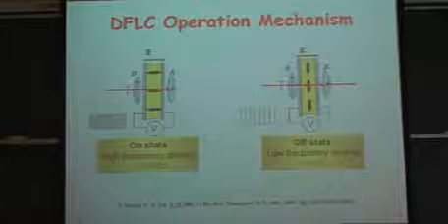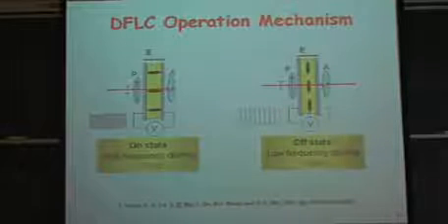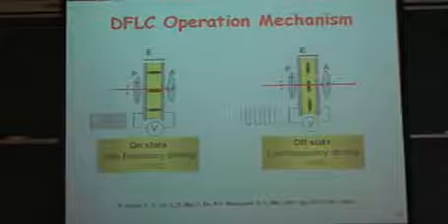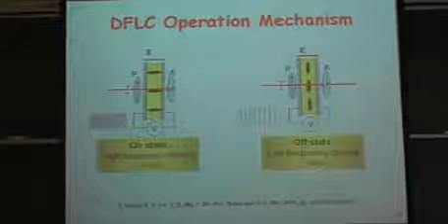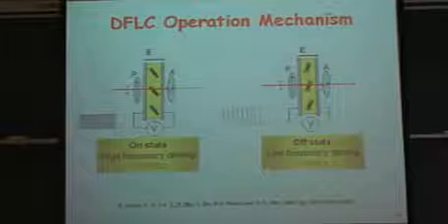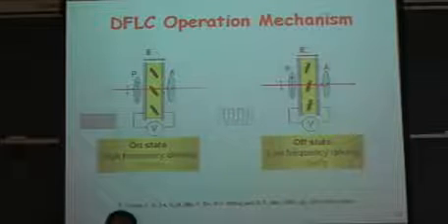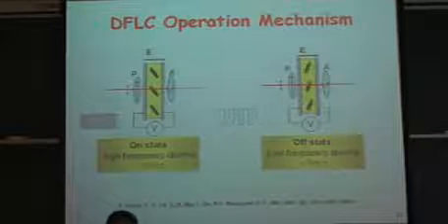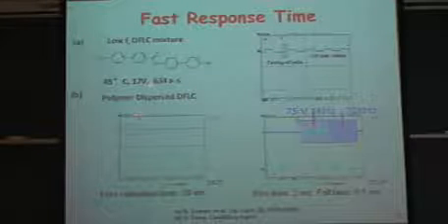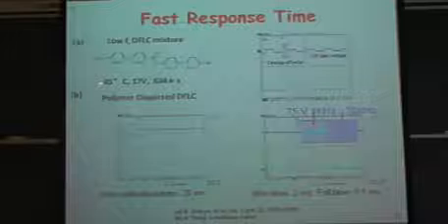Okay. Now this slide shows the dual-frequency operation mechanism. As we said before, both rise time and decay time can be assisted by the voltage. So you can see this is just the liquid crystal cell switching. When you apply voltage, this shows two results. One example is to use a low crossover frequency material and work at 45 degrees.